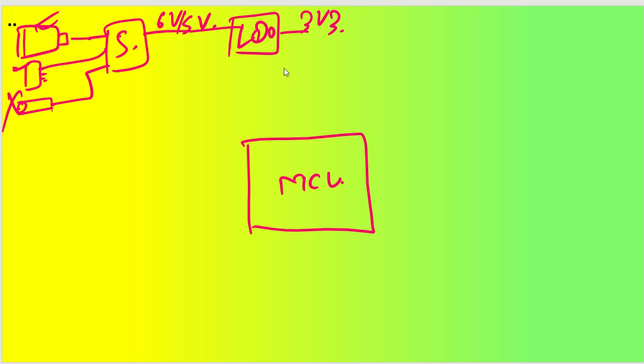We'll just define what the different blocks are that will be required. If you have lower voltage and you need a little bit higher voltage for your air pump and the air valve, then for that you can use one boost regulator also. The boost regulator can give us 6 volt if you have an input of 5 volt, right? So this is how we'll try to use it. You have to think about how to use it, or otherwise you can discard this as well. Good. So we have worked out how we can design the power supplies.